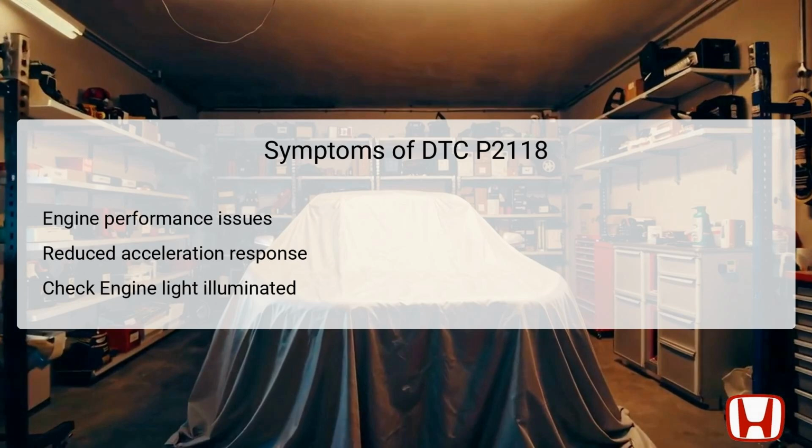Additionally, drivers may observe the check engine light illuminated on the dashboard, prompting them to perform diagnostics. Other symptoms may encompass erratic engine idle or unintended acceleration changes, which may lead to a safety hazard if not addressed swiftly. Understanding these symptoms can guide the technician in quickly identifying the vehicle's issues linked with DTC P2118.